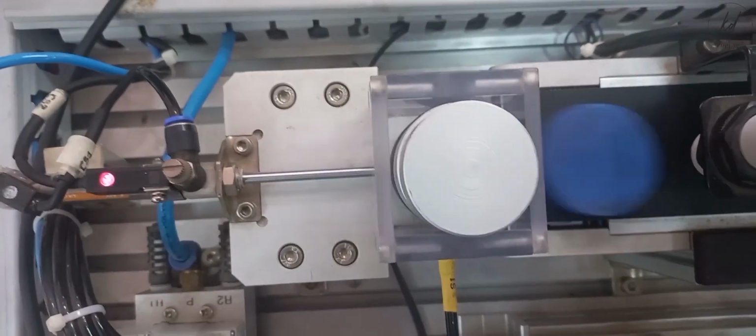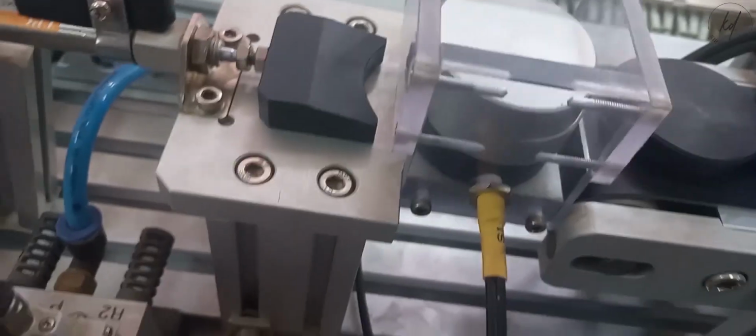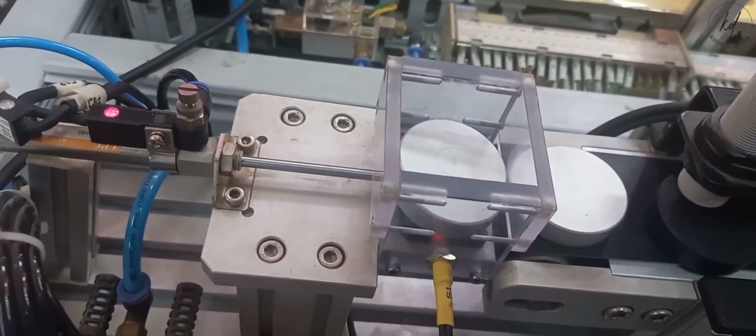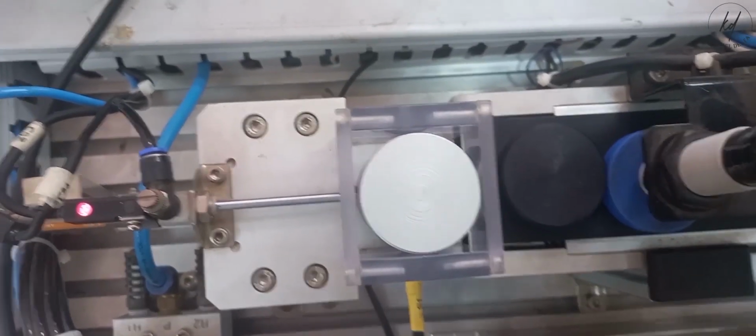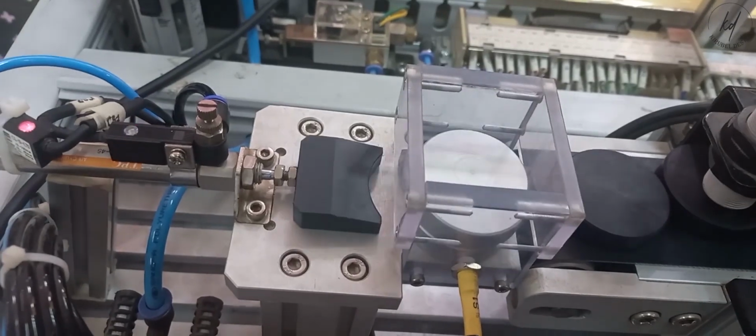Our mission is that as the start push button is pressed, the supply cylinder advances, and after 3 seconds the cylinder returns to its original position. So for this particular project we are going to use an on timer and adjust its preset time to 3 seconds, and we will get the following results.